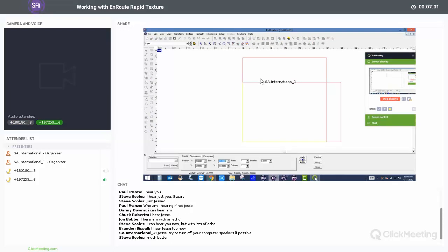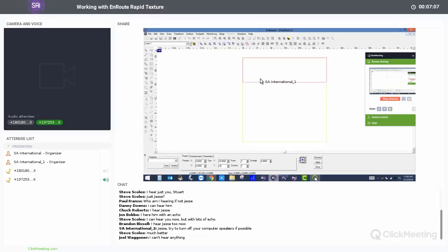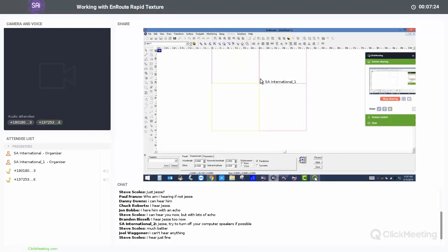So if I want to panel out a wall, I can add multiple ones. What I'm going to do is match my plate to my size of the panel as well. We'll go ahead and do a 2 by 2, so that way we have 4 panels rather than 1. My overlap, I am going to leave at 0 for this because I do want it to flow from pattern to pattern. And then really our displacement factor, this is where all of the information comes in.